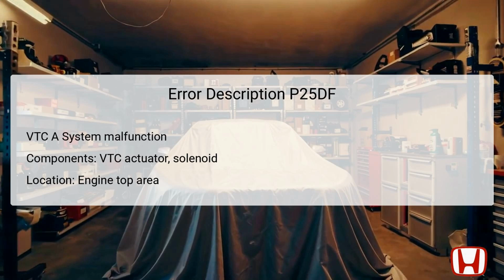The components involved include the VTC actuator and the VTC oil control solenoid. The actuator adjusts the position of the camshaft, while the solenoid controls oil flow to the actuator. These components are typically located near the top of the engine, facilitating optimal performance through precise adjustments. A thorough understanding of these components and their relationships is crucial for effective diagnostics.